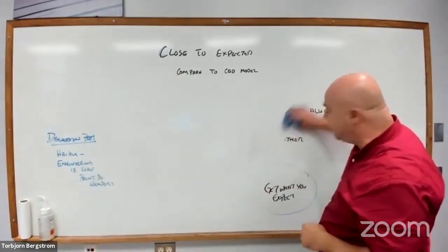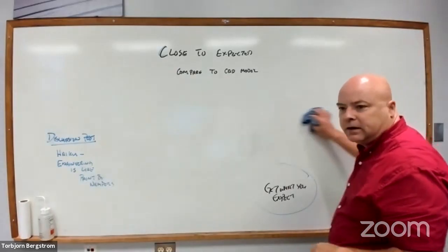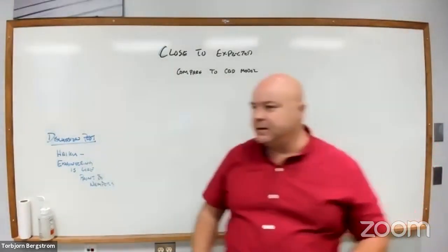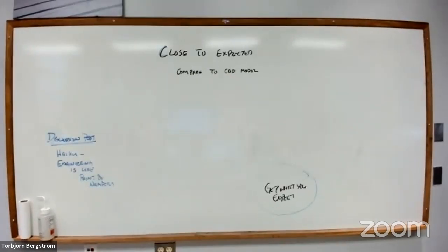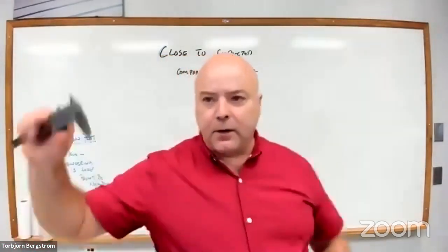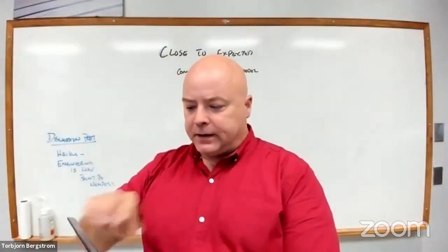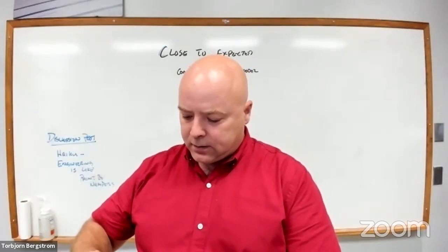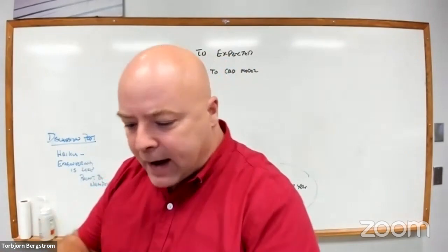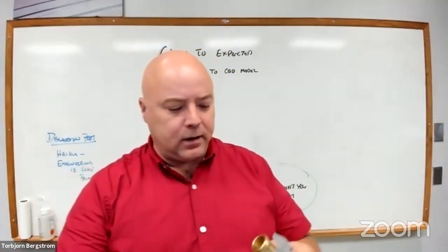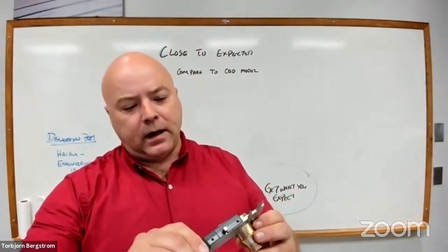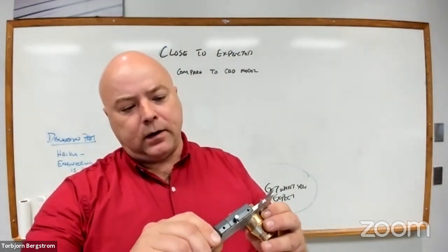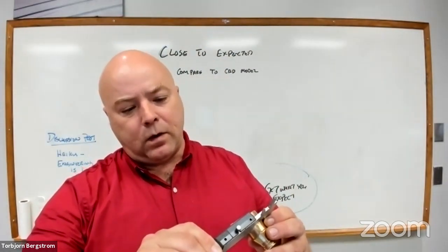So if I take my measurement tool, it's funny, I'm in a room full of measurement tools. Let me see if I can grab one. So I have my measurement tool here. It's a digital caliper. It opens and closes. It's a little bit dirty. And I can measure, let's say, the diameter of my cylinder. And I get 1.101 inches.